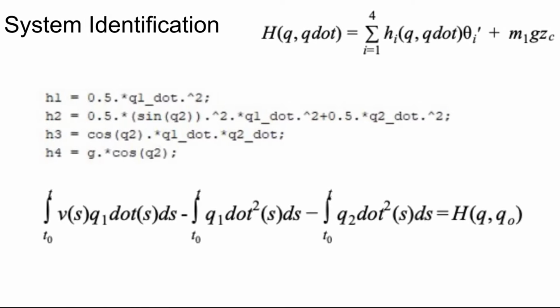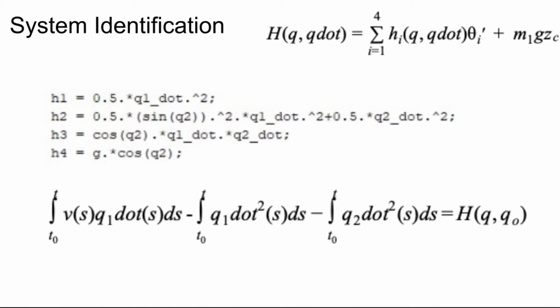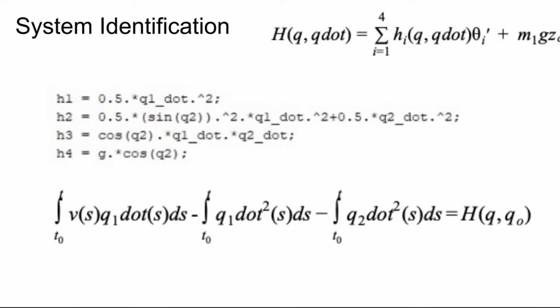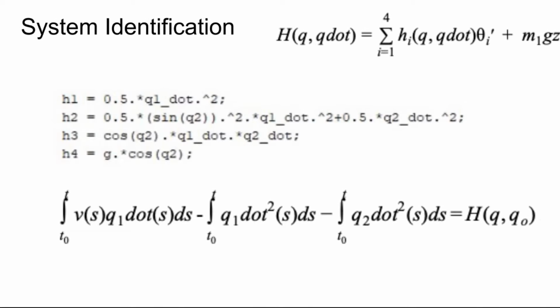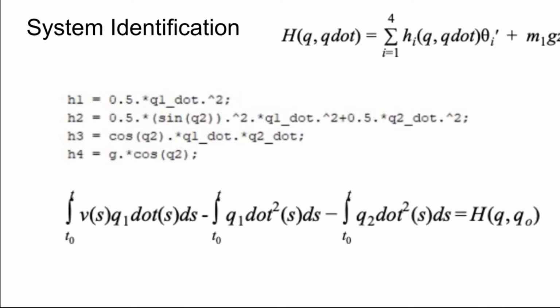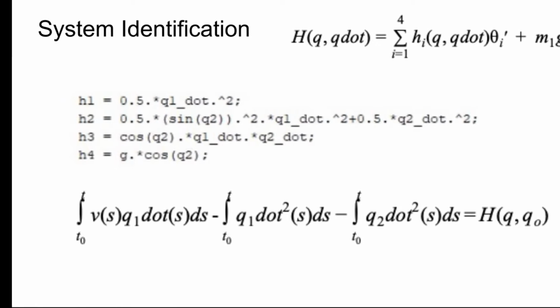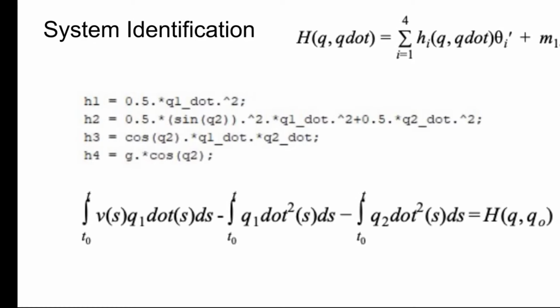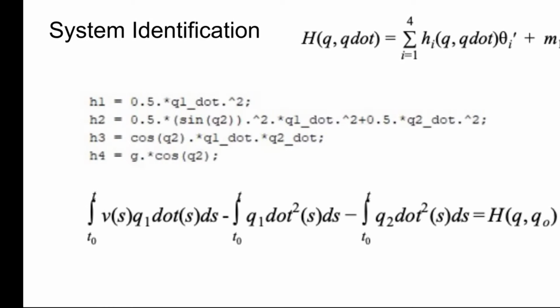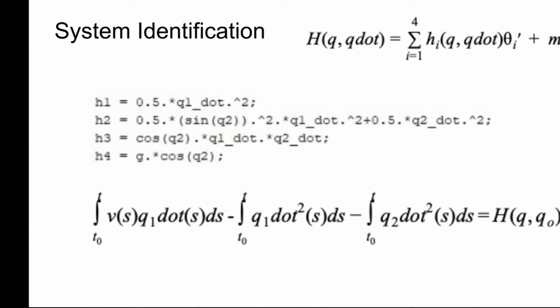The following equations were derived from the previously used Lagrangian equations of motion because the Hamiltonian is the same as the Lagrangian except for having negative velocities. The input energy was subtracted by the losses in the system due to friction when converting mechanical power to electrical power. Therefore, due to the law of conservation of energy, the input energy and loss was set equal to the Hamiltonian.